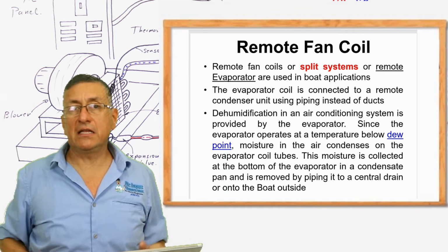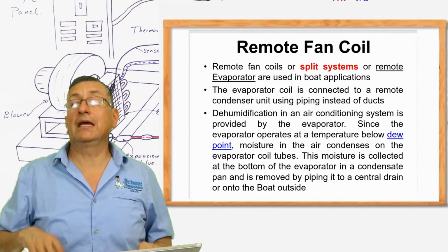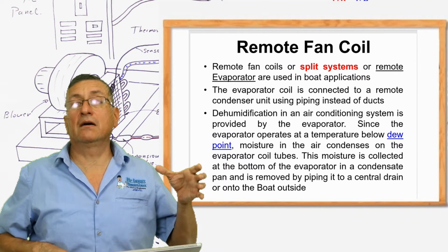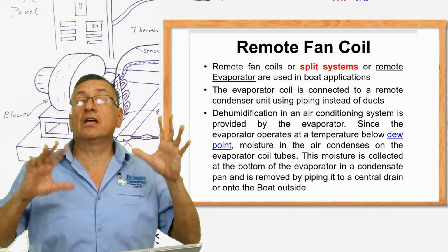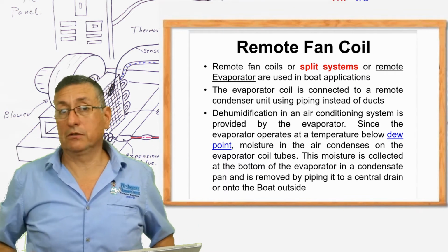25 feet separated, you have a lot of refrigerant. For that reason, the label on the compressor with the amount of refrigerant for that system probably is not enough, because it's a split unit with a remote evaporator.